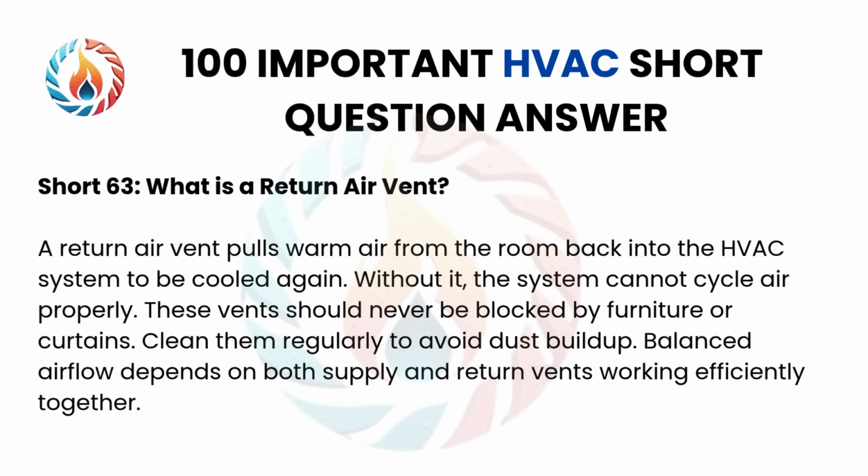Short 63. What is a return air vent? A return air vent pulls warm air from the room back into the HVAC system to be cooled again. Without it, the system cannot cycle air properly. These vents should never be blocked by furniture or curtains. Clean them regularly to avoid dust buildup. Balanced airflow depends on both supply and return vents working efficiently together.